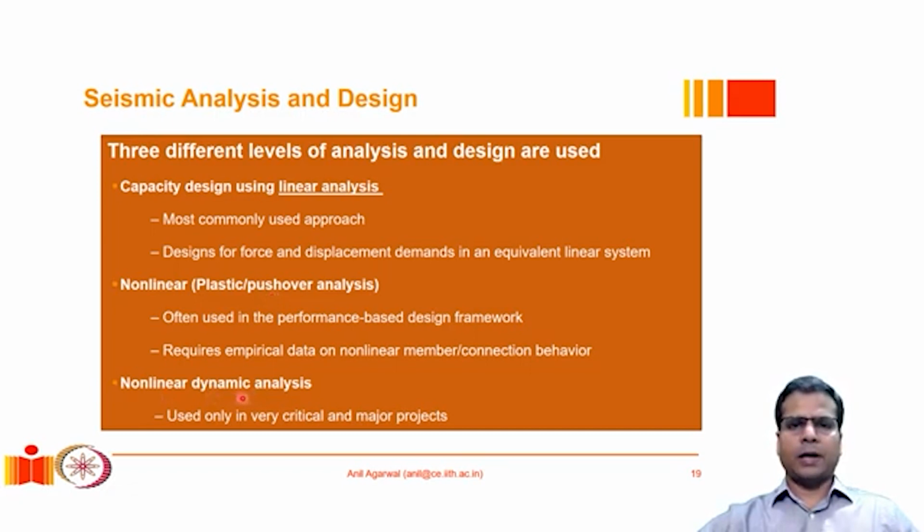In a nonlinear dynamic analysis, we actually take into account the inertial aspects of the building and also the time variability of the forces. And as a result, this is the most accurate method to predict the performance of the structure. And based on this, we can actually design individual components. But the challenge here is that having the exact information about the earthquake loading and also about the constitutive relationship of different components of the structure is very challenging, and if we make a mistake there, the results could be